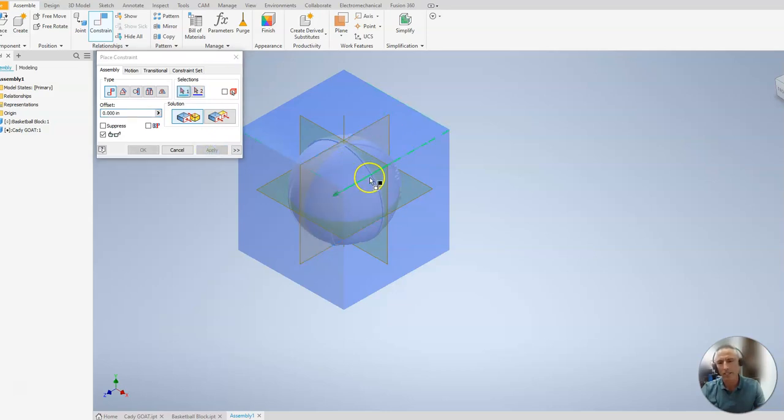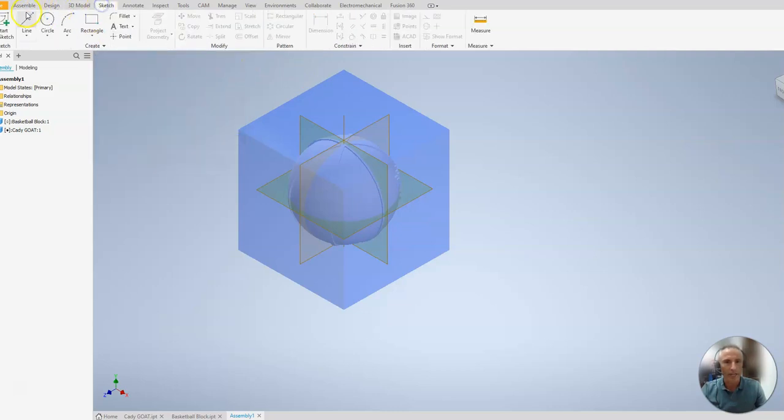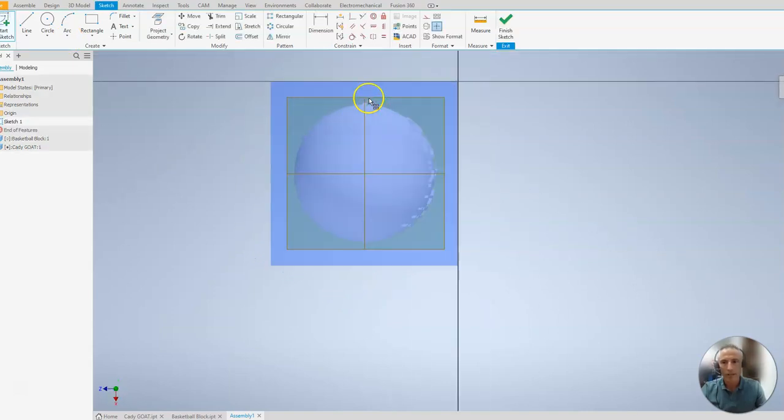Okay, now eventually that's going to be a cavity in there that we want to get chocolate into. So we need to put a spout on this, an injection site. So I'm going to close this, and I'm going to put a sketch on this top surface, and I'm going to put a point on there. Now I do want it to eventually be right in the middle, but just to show you that I am dimensioning the thing, I'm going to intentionally put it where it's not in the middle.